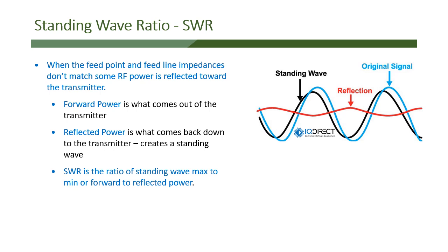And when we're trying to design an antenna system, a transmission system, we want to get that standing wave ratio as close to 1-to-1 as possible. Is it okay to be off 1-to-1? Absolutely. 1-to-2, 1-to-3, not so bad. The power losses are not significant enough that we're worried about them when we're dealing with most power situations like